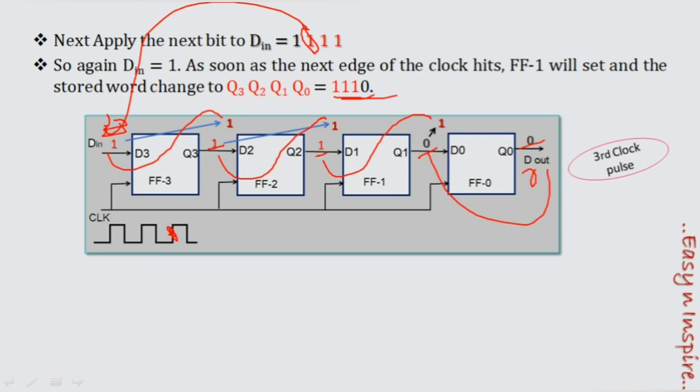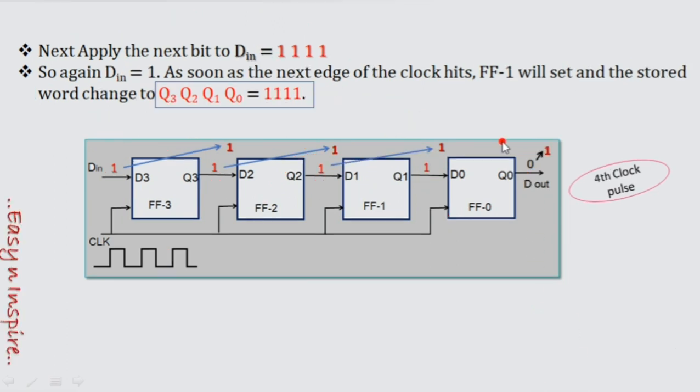Okay. Now, last stage. So fourth stage. My outputs are 1, 1, 1, 0. And now this one is going to be applied here. Always remember, whatever the input we are giving, we have to give here because we are applying in series. So for this flip-flop, I am mentioning these are my inputs. For this flip-flop, 1 is my input.